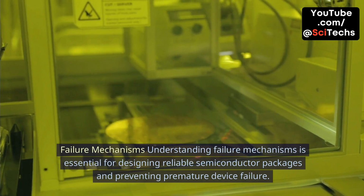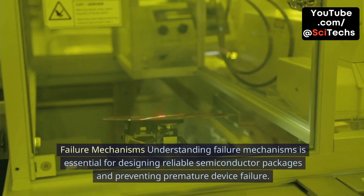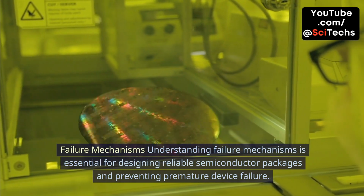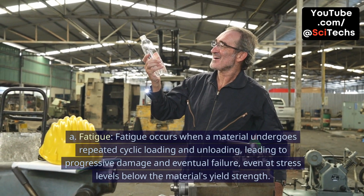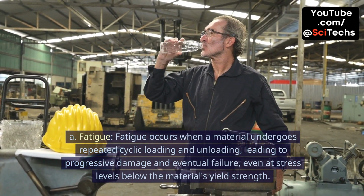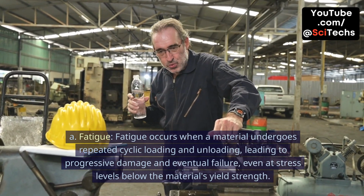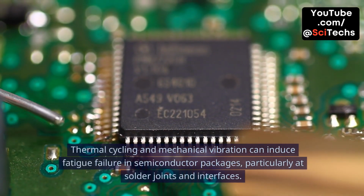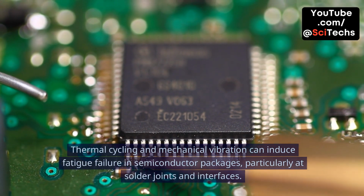Failure mechanisms. Understanding failure mechanisms is essential for designing reliable semiconductor packages and preventing premature device failure. A. Fatigue. Fatigue occurs when a material undergoes repeated cyclic loading and unloading, leading to progressive damage and eventual failure, even at stress levels below the material's yield strength. Thermal cycling and mechanical vibration can induce fatigue failure in semiconductor packages, particularly at solder joints and interfaces.